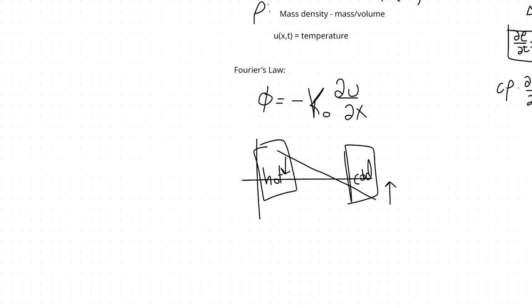So he noticed a proportion where the flux is proportional to the change in temperature over some distance. So over this distance, because the temperature goes from hot to cold, you see the hot reducing and the cold increasing, right? And I should put a minus here, I forgot. And so then you can convert this to an equation by just putting in a constant, and this constant k naught is just thermal conductivity, which is again just a property of a material that you can figure out empirically.